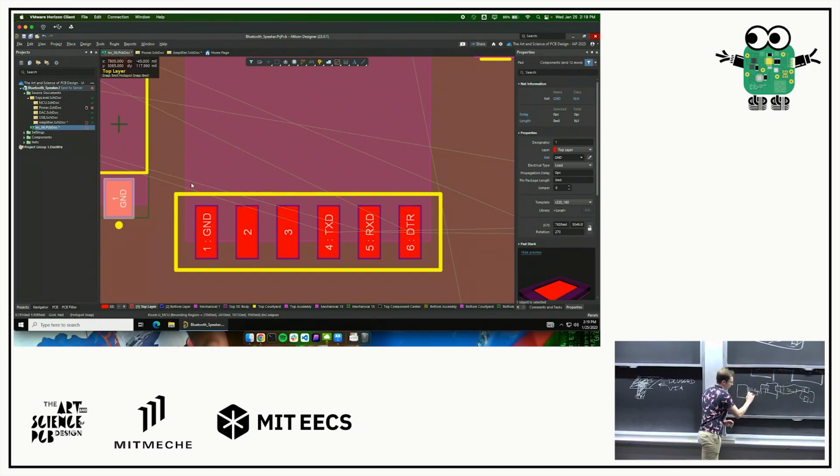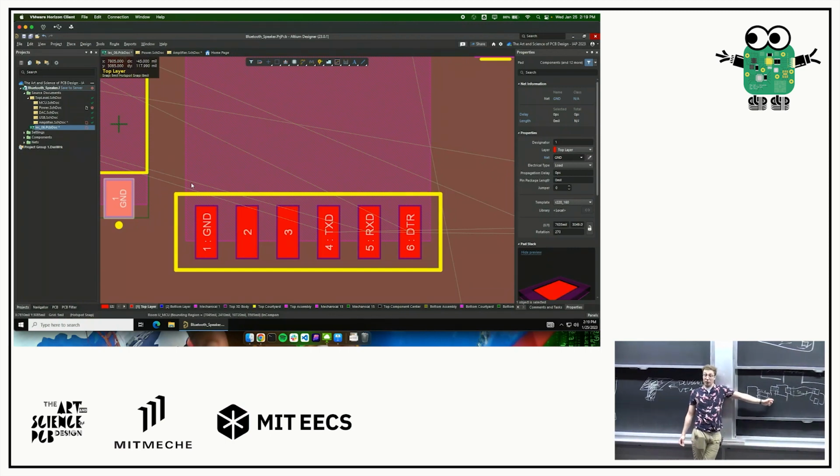And if we try and put these next to each other, oh no, my traces are on top of each other. That'd be a good cause for making that smaller, because if any of those pins were designed for a lot of current, the manufacturer probably would have put a bigger hunk of metal on it, right? So if the manufacturer says that 8 mil is fine for the actual part, then that's a good suggestion to maybe only use an 8 mil trace there. Does that check out? Sweet.